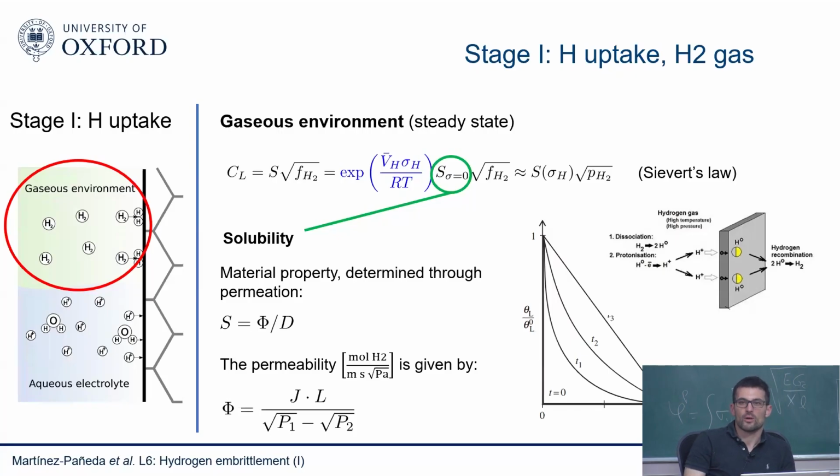For example, if I have a very small membrane of a ferritic steel, like a pipeline steel, it will take maybe 1 hour and I can do my test. I can see the flux of hydrogen coming out on the other side. If I have something like this of an austenitic steel, I need to wait a month. So the difference can be quite significant. A lot of people say, okay, maybe we can use membranes that are very, very thin, and then I can reduce the time of my experiment. I don't want to be waiting for a month.